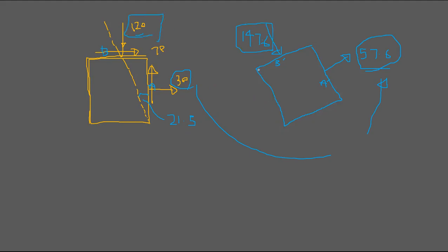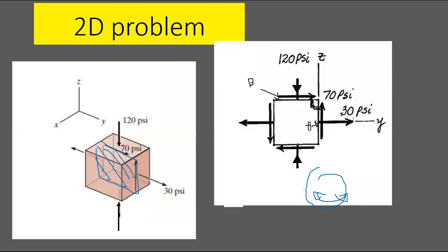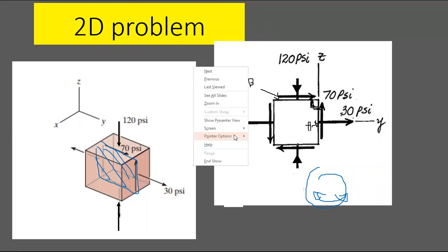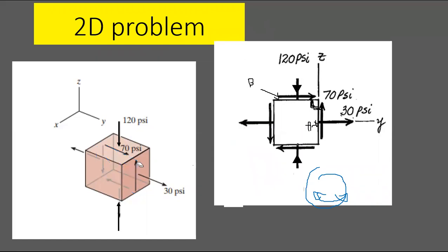And actually there's a plane where you have this kind of stress, right? So in order to find this, we use the Mohr circle, right? That means there's a plane in this element, right, which undergoes pure compression and pure tension, larger than these values.